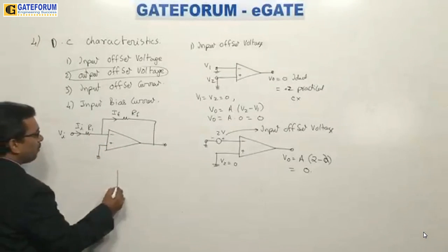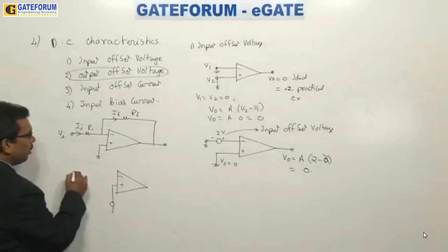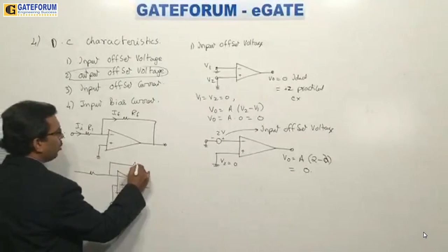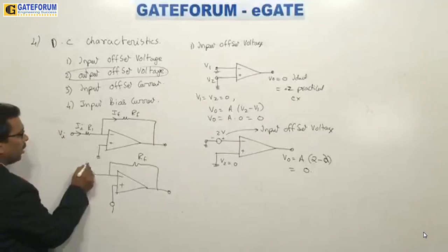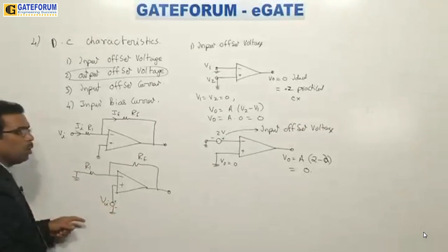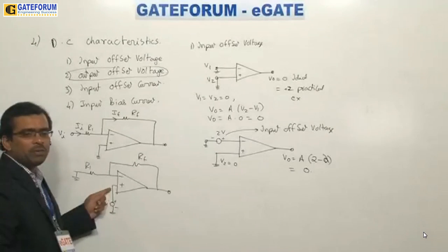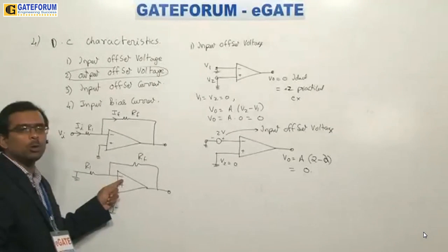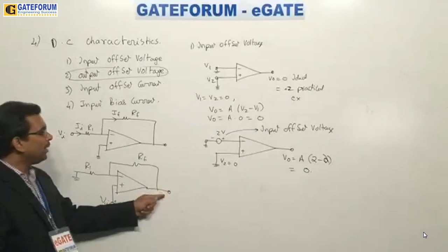And the next thing we have here is the non-inverting amplifier. I give the input here like this, and I ground it here like this. Now the op amp is considered a voltage amplifier. No current will enter into this, but definitely this voltage will appear as input to this, and that voltage will appear in amplified form here, and that is fed back.